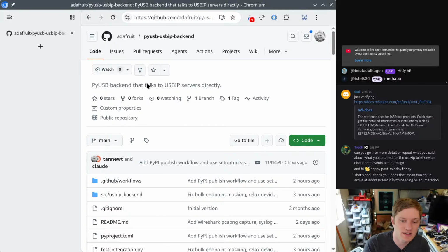So in this case where I just kicked off this thing to be a logic analyzer, I think the way that I'll bridge it upwards is I will pretend there's another USB device plugged in for this logic analyzer code, but it actually runs in the same CPU, the same microcontroller. But that's my theory. I don't have that working yet, but the idea is that I can use a hub to plug a bunch of stuff in on the hardware test side, and then as I realize what I need exactly, I can integrate it back into the same thing to cost it down.